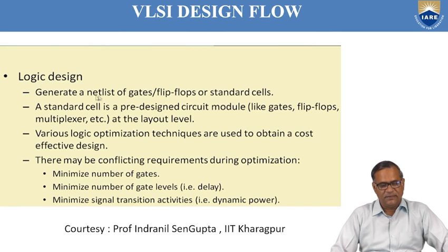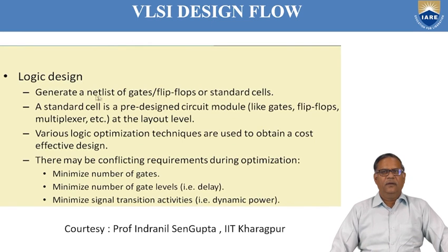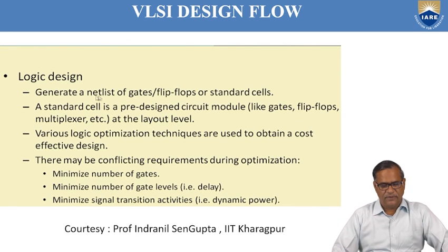Now next comes the logic design. In logic design, we generate a netlist of gates or flip-flops or standard cells. What is a standard cell? It is a pre-designed circuit module at the layout level. And there are various logic optimization techniques that are used to obtain a cost-effective design. Of course, here we have conflicting requirements of optimization, like you cannot optimize area, power consumption, and speed at the same time. So there are conflicting requirements during optimization.